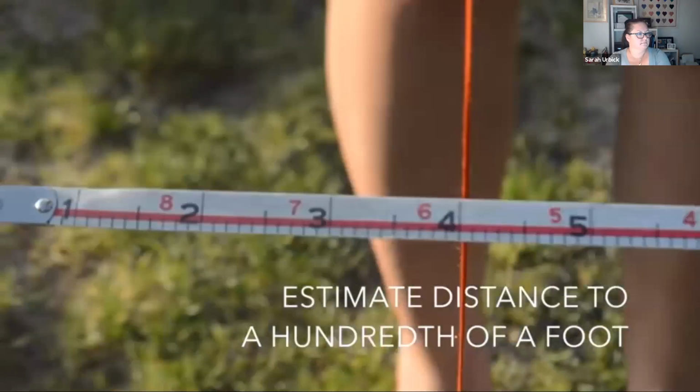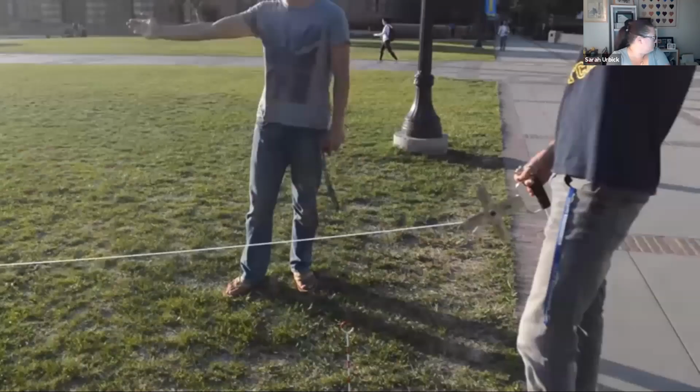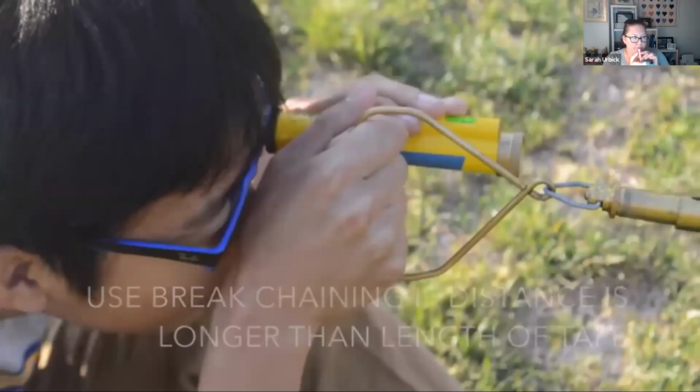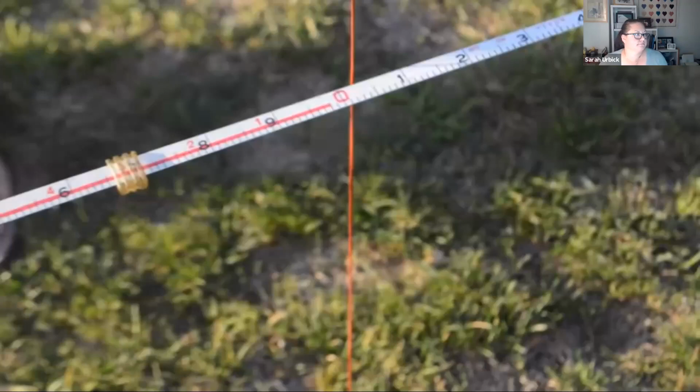Record the complete measurement. If the distance you're measuring is longer than the steel tape, in this case 100 feet, you will have to divide the distance into 100-foot segments in a process called break chaining. Follow the same procedure as before with temporary endpoints and starting points at every 100 feet. Record the final distance.